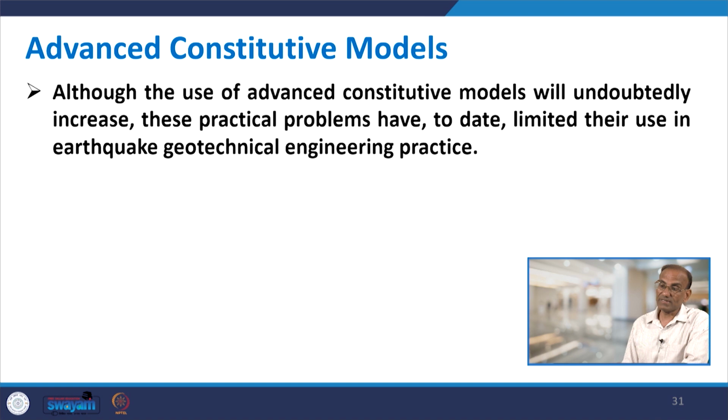Although the use of advanced constitutive models will undoubtedly increase, these practical problems have to date limited their use in earthquake geotechnical engineering practice. Still, their use is continuously increasing, and a number of advanced constitutive models are already available, ranging from von Mises, Drucker-Prager, then incremental models, and then the HISS model also.